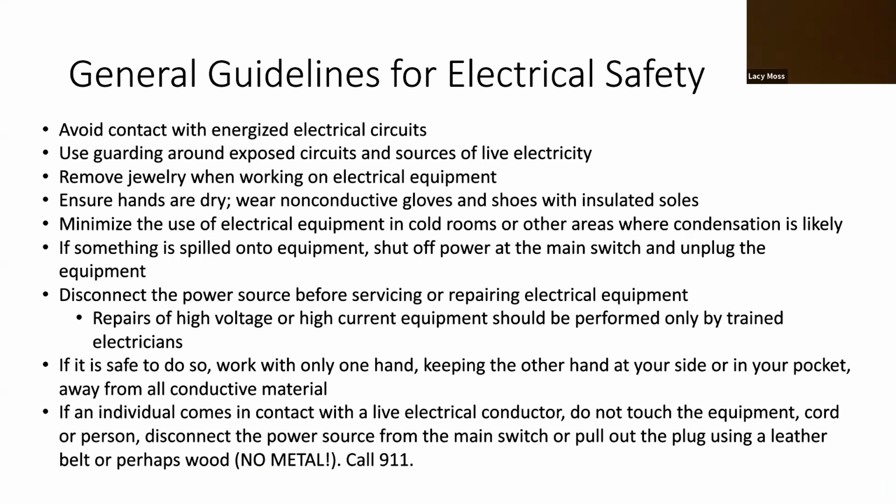Ensure hands are dry. Wear non-conductive gloves and shoes with insulated soles. Minimize the use of electric equipment in cold rooms and other areas where condensation is likely. If something is spilled onto the equipment, shut off the power at the main switch and unplug the equipment, and then deal with the spill. And make sure you let it all dry out before you turn it back on.